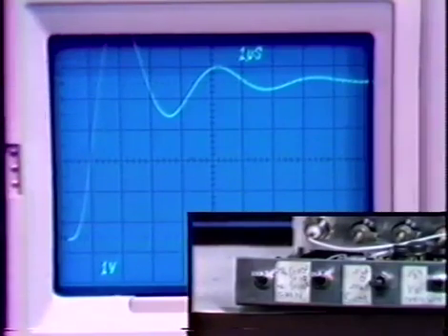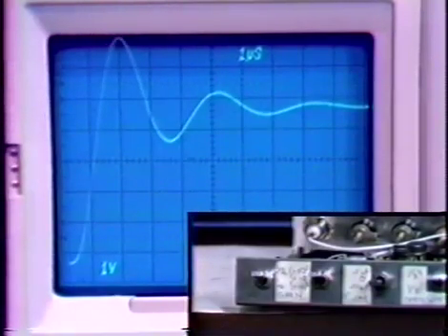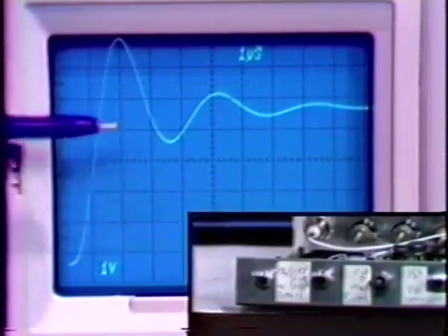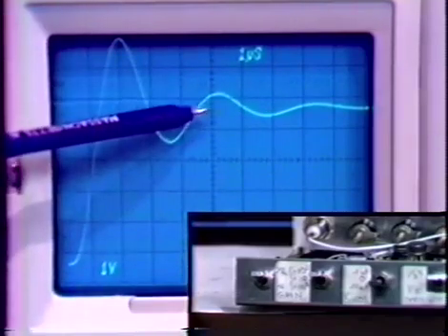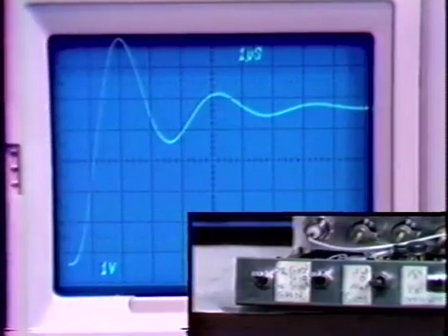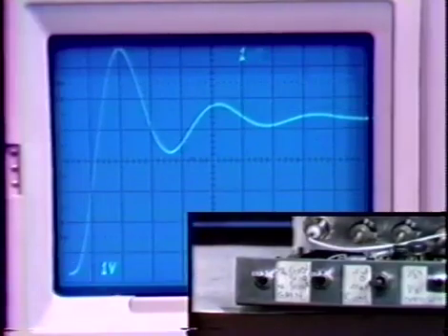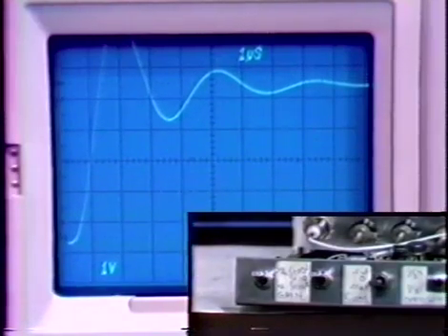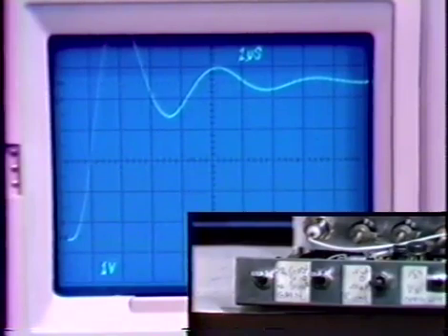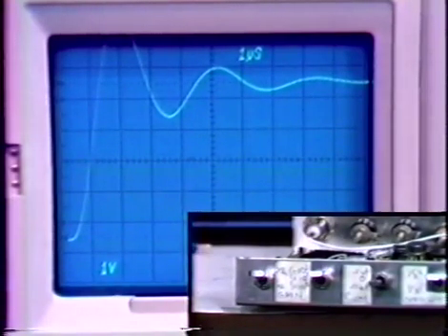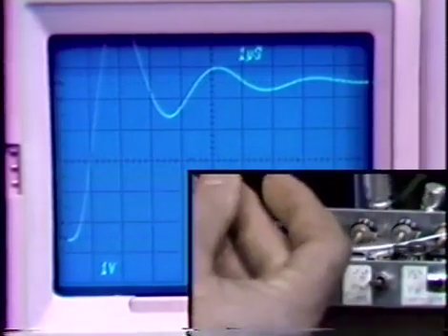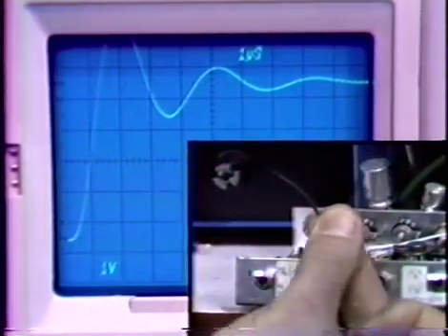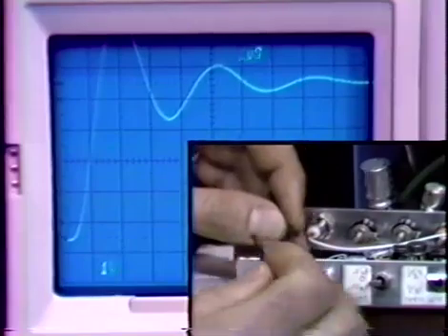We notice considerable overshoot to the step response with no compensation. We see there might be something like 30% overshoot or 40% overshoot. Reasonably high frequency ringing at about 300 kilohertz. We have 1 microsecond per division horizontally now. So let's see if we can compensate that. If we really believed our numbers, we'd conclude that we needed 20 picofarads divided by 1,000, and that seems somewhat unrealistic. Actually, we need a capacitor a little bit larger than that. But let's get our capacitor this way. I simply have 2 pieces of wire that I'll put into the compensating terminals.